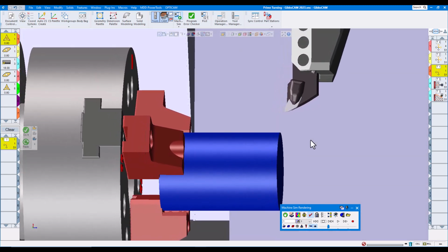And the nice thing about prime turning is you can go very high feed rates. In inch mode, we've been turning a lot of them at 20 thou per rev and 1/8 of an inch or deeper radial cutting, and that works very well.